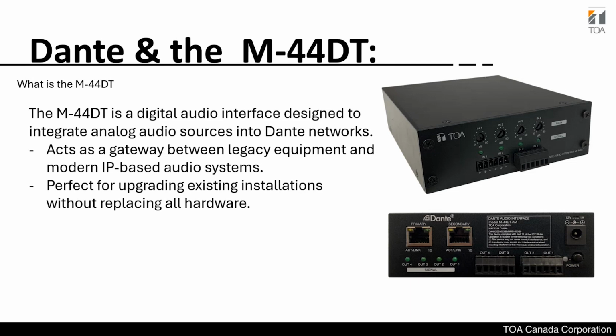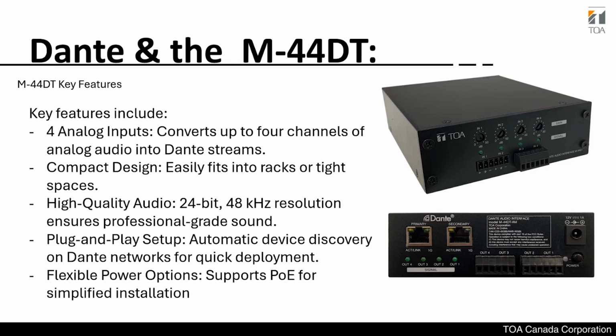And we can also use it in the opposite way. For example, we already have an existing amplifier and we don't want to replace it with a Dante amplifier, or add anything else there. We can just use this device, take the output from it, and send the audio to the existing amplifier. As we discussed, we have four analog inputs. It converts up to 4 channels of analog audio to a Dante stream, in a compact design.